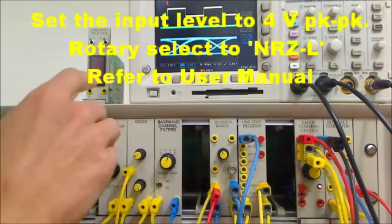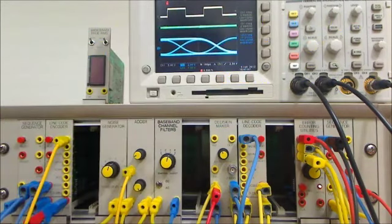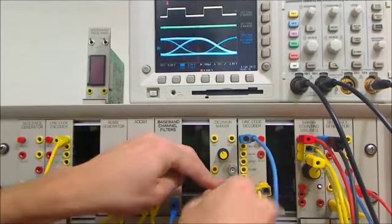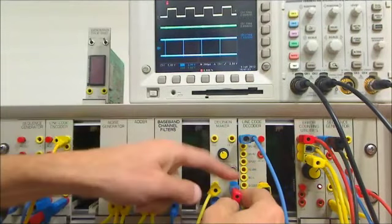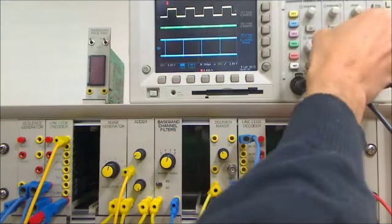We're on 2 volts per division, and we'll set this up to be 2 volts peak, 4 volts peak to peak, so the thresholds are correct. We have the optimum level, we have a decision point in the middle. Now view the output from the decision maker. You can see that it's a cleaned up line coded version of the input.